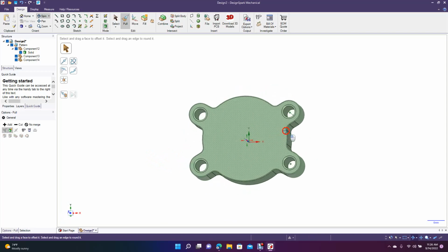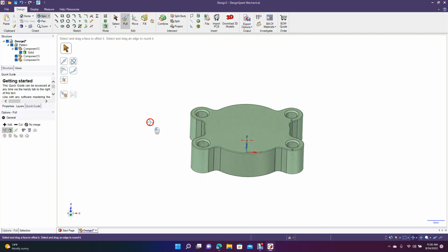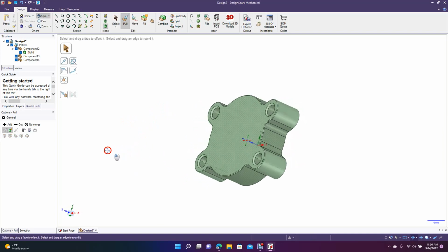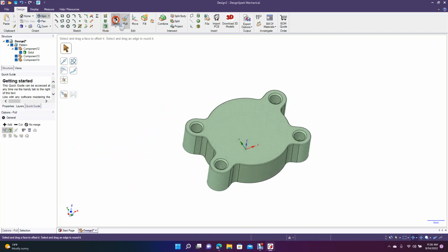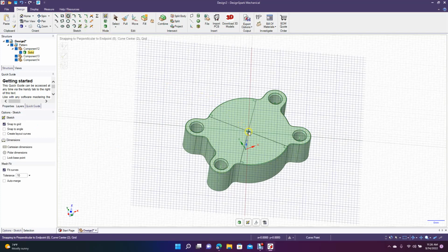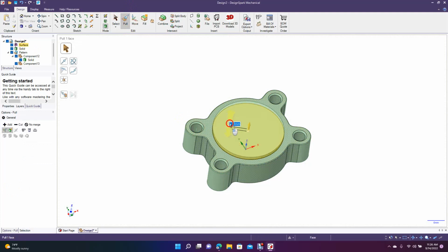Then over here we added a 0.5mm chamfer on this. So this is going to end our part. The only other thing I might like to do is maybe add a different kind of top to this. So we'll go create a circle here. Maybe I'll add a 25mm piece on top here. Make this model a little more interesting.